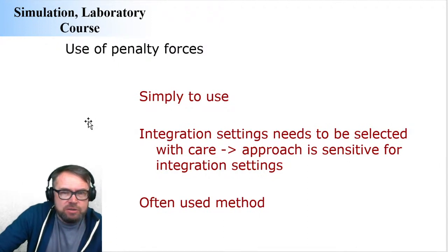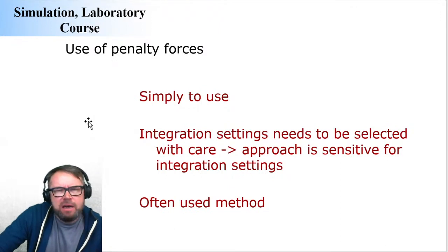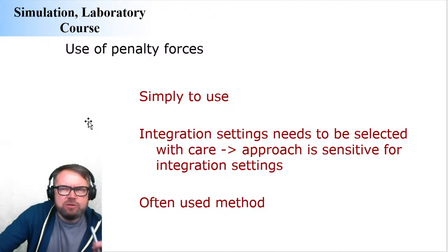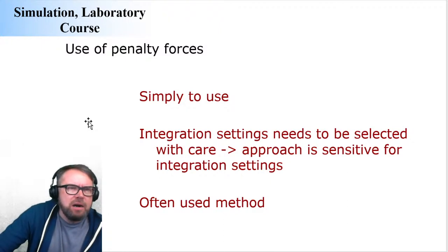There's a big problem associated with the method. And the big problem is that it is typically very sensitive to integration settings. And typically it requires that the computational time steps have to be small enough. And that's simply because it's based on the penetration. And the force is a function of the penetration. And typically there's no upper limit how much the penalty force can be.